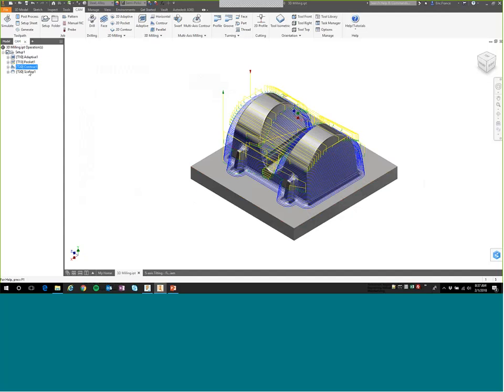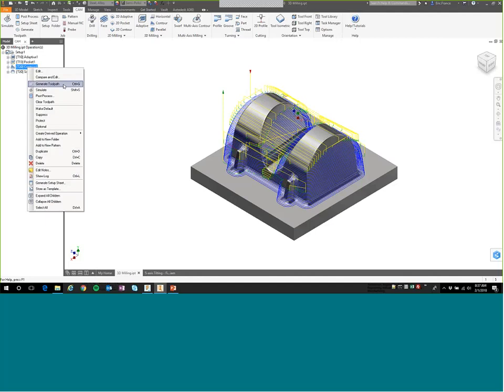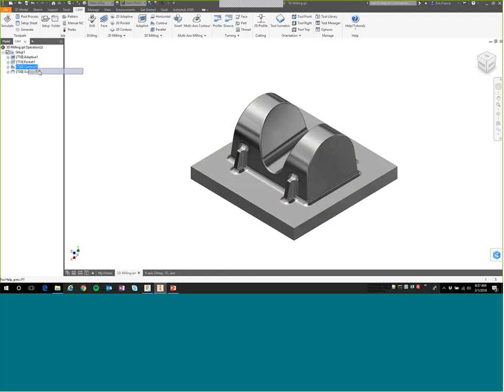And we're actually using two different operations. Contour following around, moving from the top down around each of the humps that we've got on either side of this, and then a scallop to clear off the top, real nice and even. But what I want you to notice in here is that we're using some settings in the tool itself to do some containment. That contour isn't going all the way up.